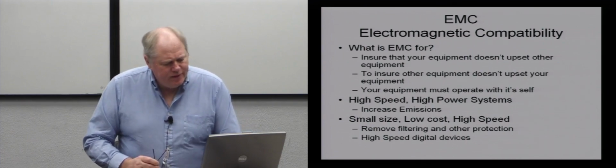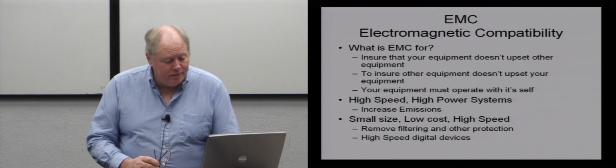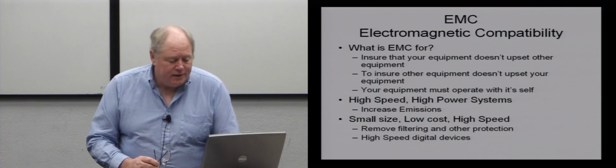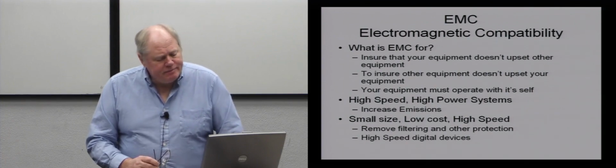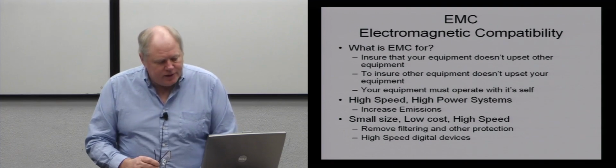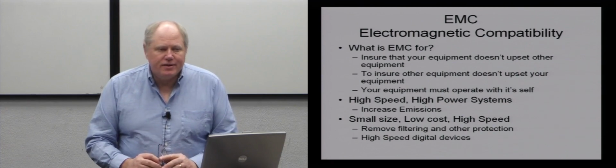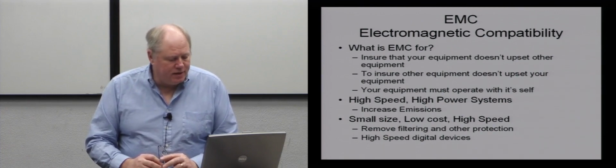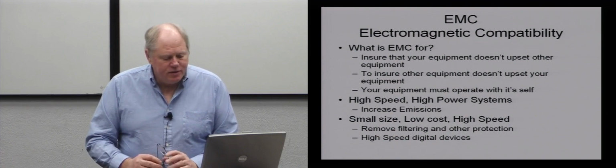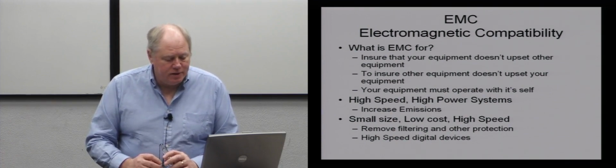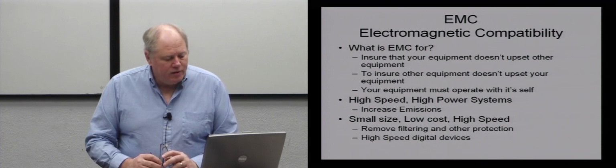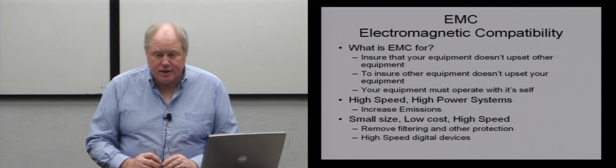And probably one of the things you might not think about, but it ends up being a problem quite a bit, is that your equipment has to operate with itself. There's a lot of noise inherent in things that switch, and the first thing that you have to do is make your equipment just work. There's a lot of noise issues that you'll come up against and fight. That's not so much an EMI thing as far as being regulated, but the things that protect your equipment from others and vice versa are the same kinds of things that help it just operate itself.